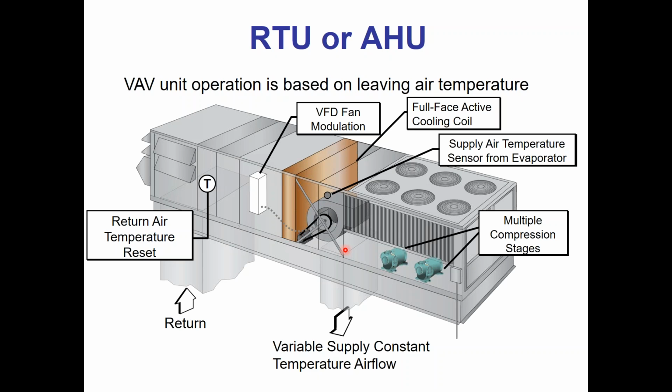It only matters because sometimes when it goes into morning warm up and it's actually running the gas heat, you'll look at the supply air temperature sensor and be like, dude, why is it like 60 degrees? What the heck's going on? This heat's full blast. It's 60 degrees because it's upstream of the heater. So your building automation system can't tell you what the discharge air temperature is on the heater unless you add some supplemental sensors in the duct system.